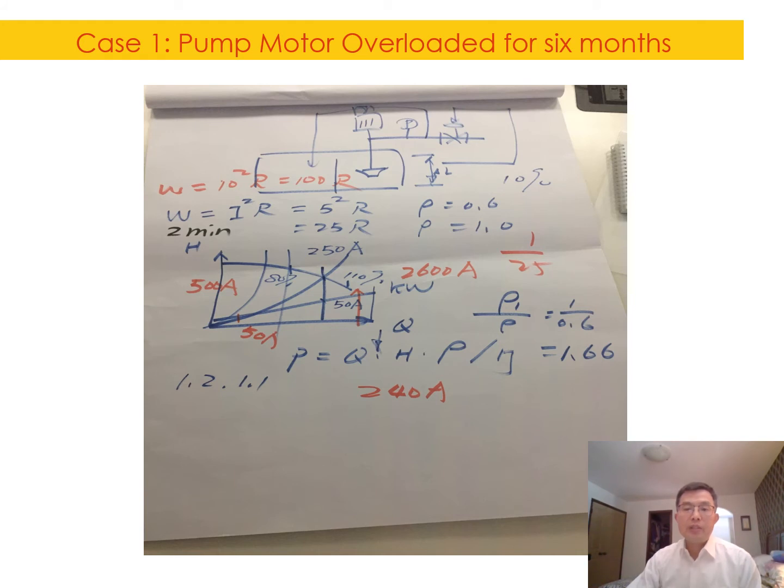and divided by efficiency here, right? So at that time, we asked the team over there how they started the pump. They told us that every time they open the discharge valve at the same position. That means according to this performance curve, it is always working at 100% here, right? Or the working position here. So no problem. That means the power needed is no different from before, correct?